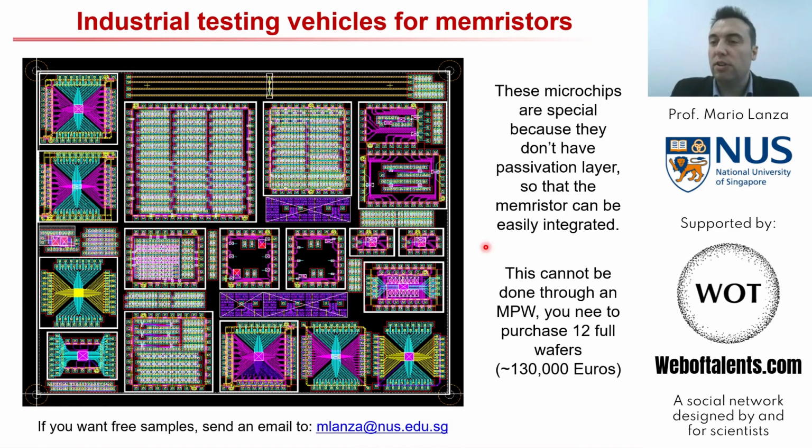In this way, when we receive the sample, it will be a little bit oxidized and contain some contaminants, but we have already demonstrated in a previous article published in Nature in 2023 that this can be overcome. This oxide can be etched, the samples can be cleaned to expose the vias, and then one can integrate bottom electrodes, resistive switching medium, etc. In fact, I will explain this in my next video.